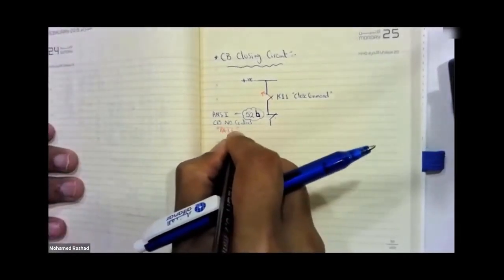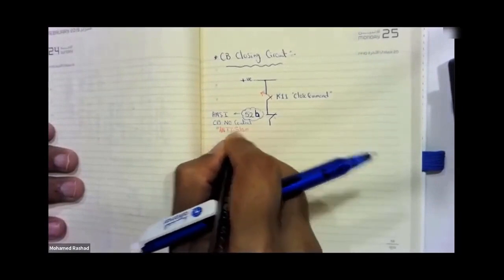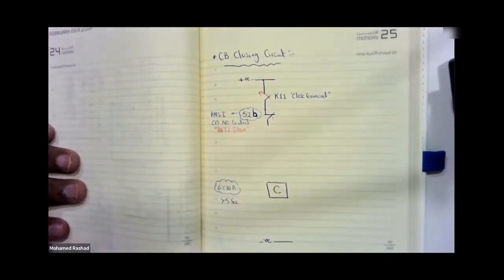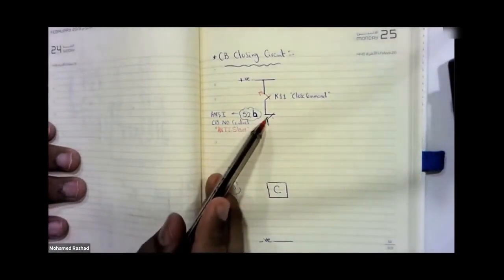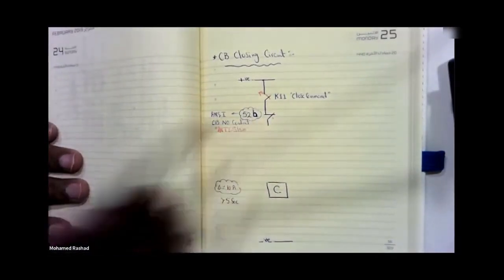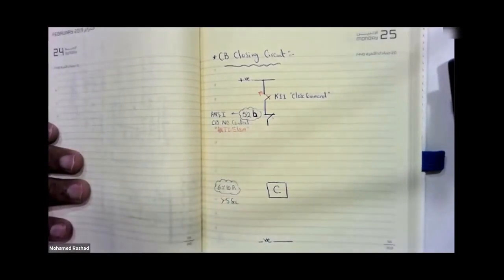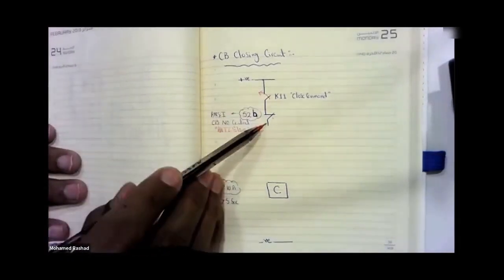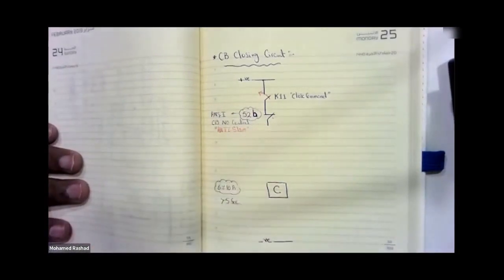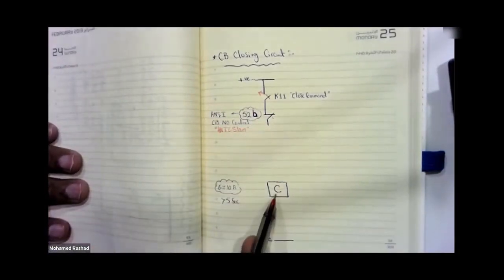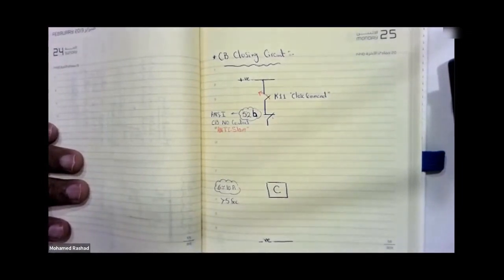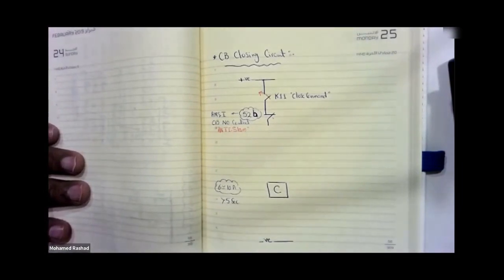The anti-what? The anti-slam. Okay, so the anti-slam engineers, what is it exactly? It is a normally closed contact from the circuit breaker, which is 52B, placed in series with the closing coil to inhibit it. This is to prevent you from giving a second close command to the circuit breaker if the circuit breaker is already closed, to prevent the coil from burning out. It cannot draw that current for a long period, more than 5 seconds, it will burn out. Oh, exactly. Okay, great.